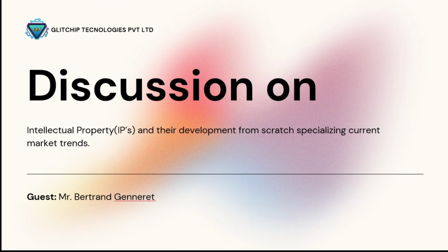Once you're done with the RTL design, the next step is the functional verification of your code. You verify the RTL code to guarantee that it meets the specification. For this purpose, you need to create test benches, and you need to run simulations to check the IP functionality under various conditions.